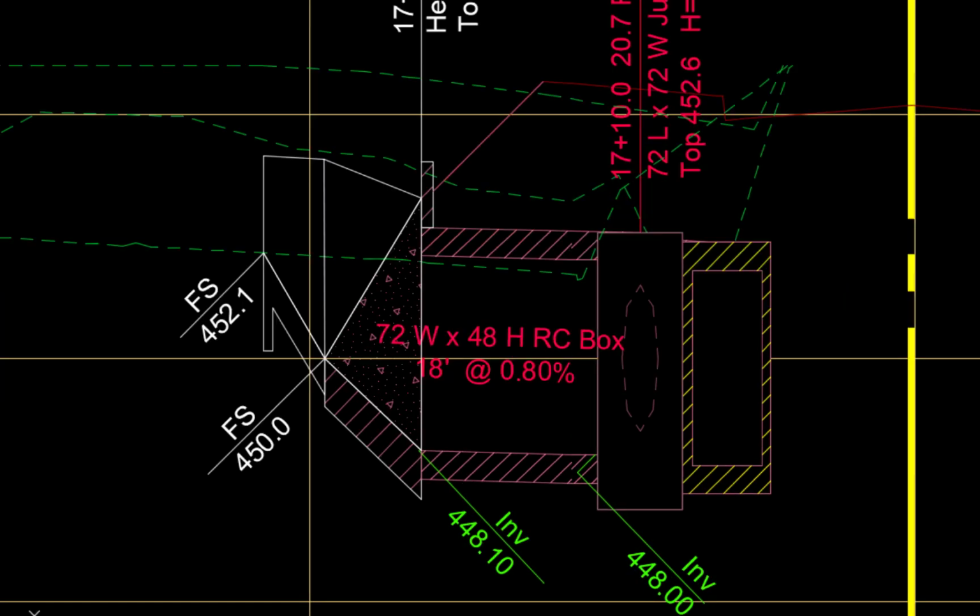6-inch thick concrete slope paving is constructed along the bottom and side slopes of a channel to prevent erosion. The slope paving associated with the wing wall and head wall is drawn in profile view. The bottom of the slope paving has the same width as the RC box and extends upward from the floor of the wing wall at a maximum 2:1 slope until it intersects the channel grade.